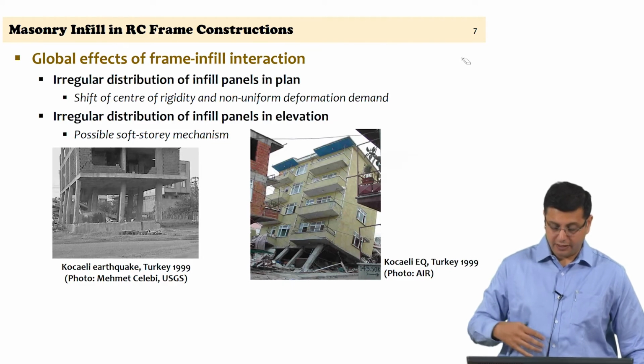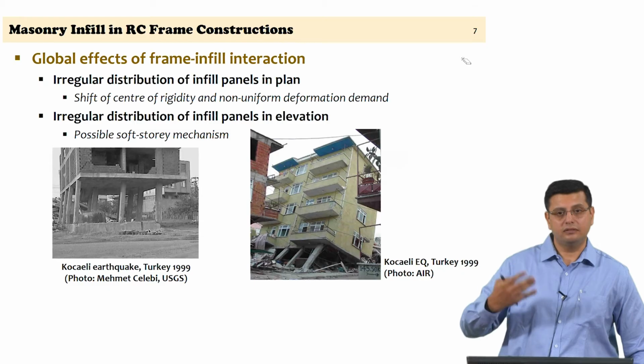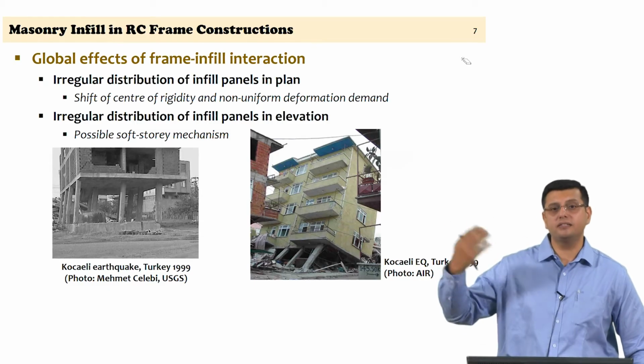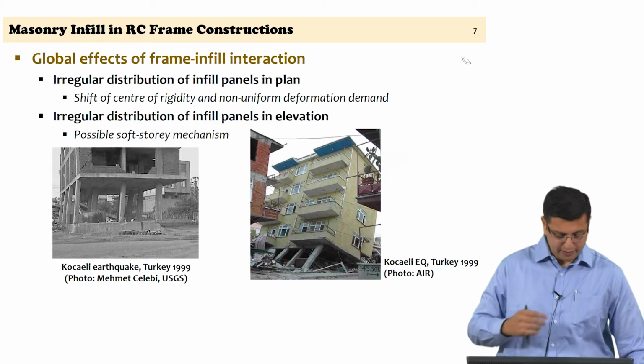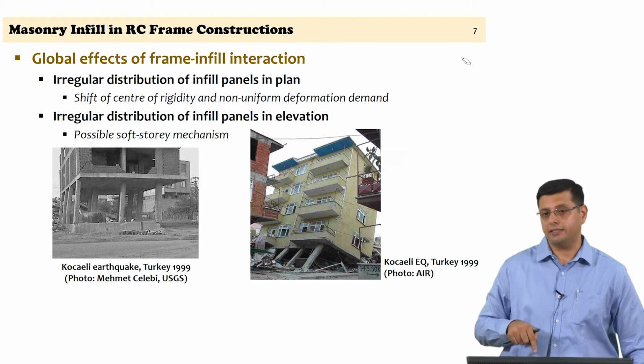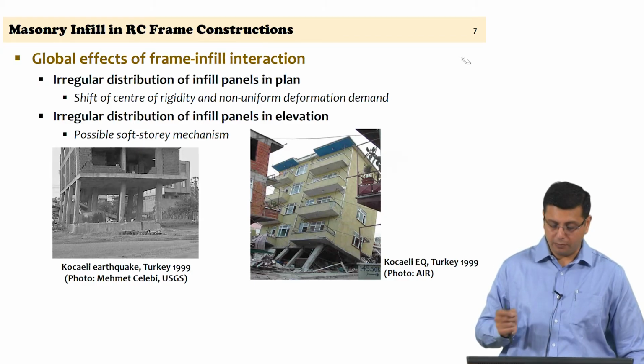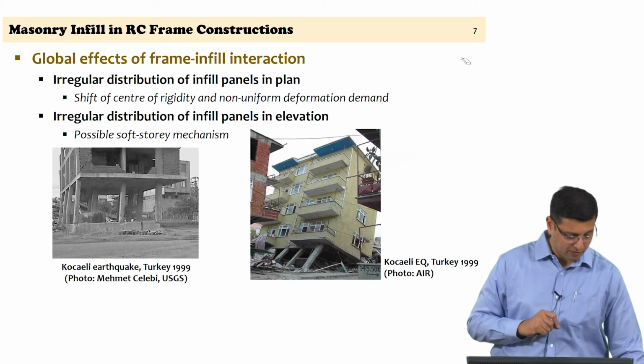in these pictures. You can see that the upper stories have almost survived without any non-linearity, any inelasticity, simply because there is a certain uniformity and higher stiffness in those stories, whereas the weakness is in the region where it is a bare frame action and not the interaction that is available because of the presence of the panel itself.